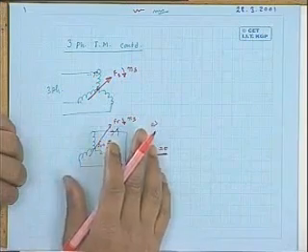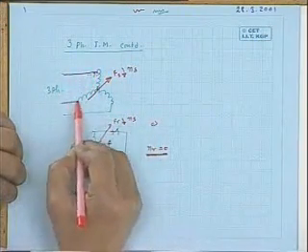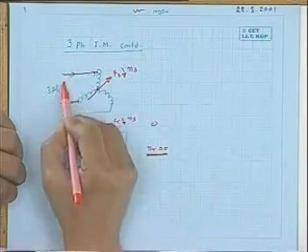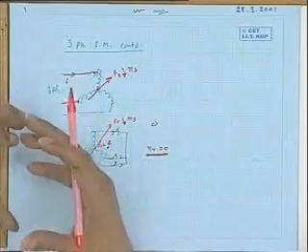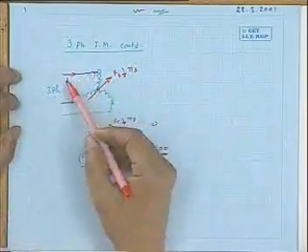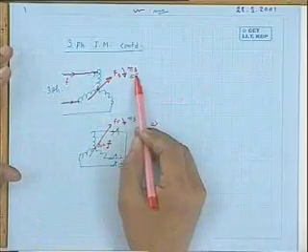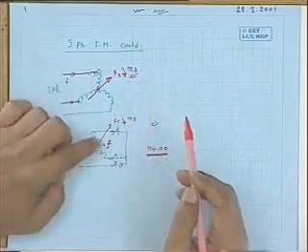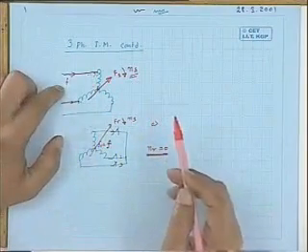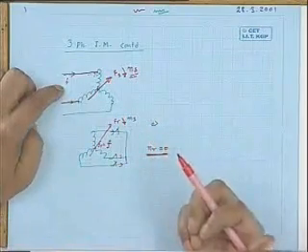Therefore, the stator, by drawing extra current, can draw only 50 Hz current, and that it will draw. And I know that by drawing 50 Hz current from the supply, the stator will produce a rotating field of speed ns. Therefore, the stator can counterbalance such a field if required by drawing extra current from the supply.